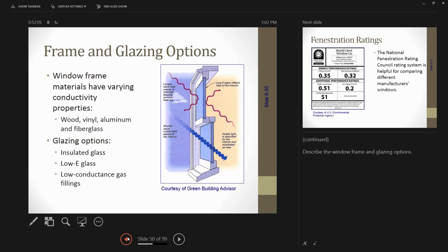So did you all read, you go through your book, do you understand how low E windows work? They reflect the longer waves back out at certain angles, but they allow them in. And so what they're doing is they're trying to block against excessive heat gain when the sun's high in the sky, and then they're trying to allow that to come in when we've got the winter sun.